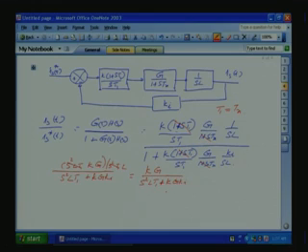So, what I want to say here is, just like that we cannot use the PI controller; everything depends on the plant transfer function. But the whole thing is coming from our converter model. This is only in our controller. So, how will we be able to choose our controller now? PI controller is not possible.